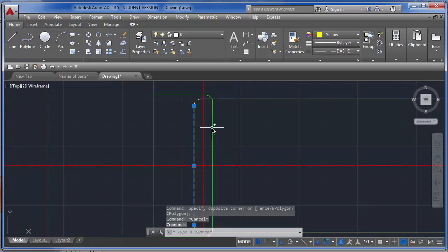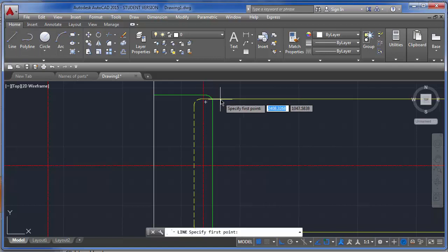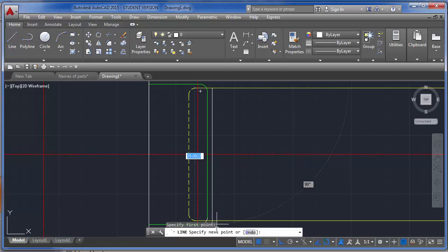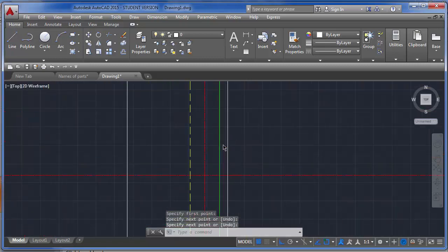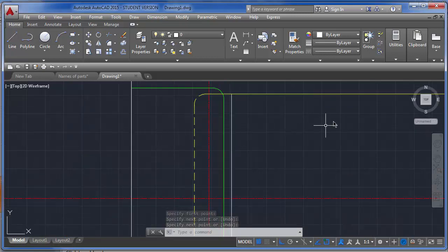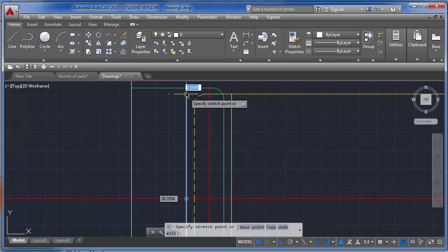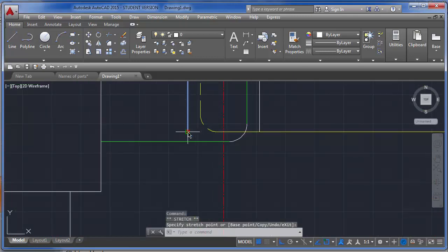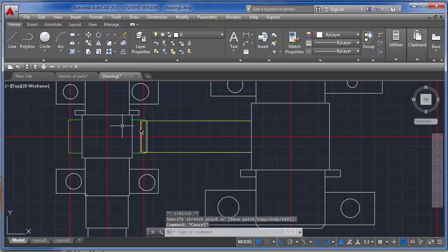So this small gear ends here, and big gear, it has a bottom of teeth, right? So this is the bottom of teeth of this side gear, this big gear. So this is clearance, bottom clearance, and this is like module by 4. So if this is 2 millimeter, this should be 0.50 millimeter. So we do the same. We just mirror this one about this guy, match it up. Okay, I have the idea now.